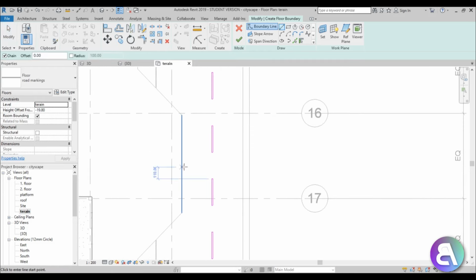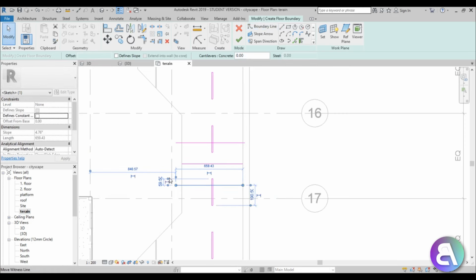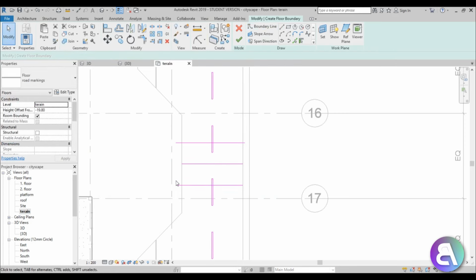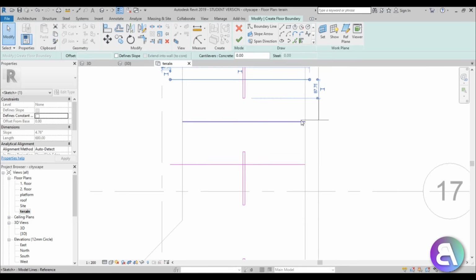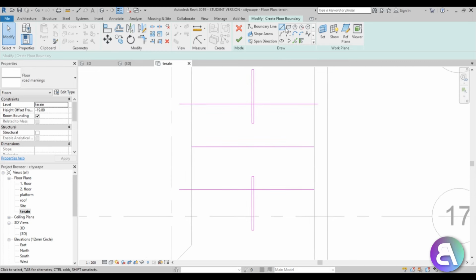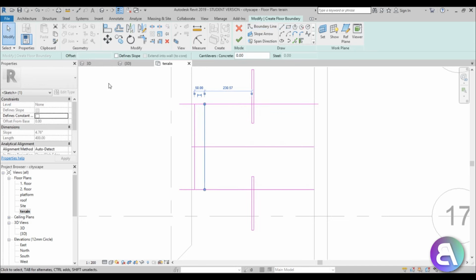So for our crosswalk, let's place a line here. So this will be the center, and the width should be around, let's say, 3 or 4 meters. Let's see, what's this distance? Let's try that again. Yeah, let's do a 4-meter crosswalk, so this should be 200. This one should be at 200 as well. So that's the size, and then let's just place a rectangle like this. And this distance, let's do 50, and delete these 2 lines.